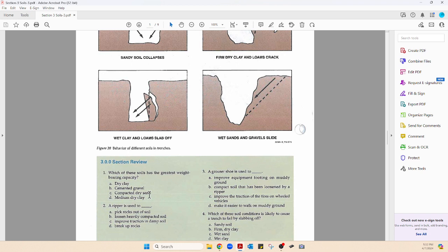You can't just put a pile of sand down and build a pad. It won't stand up on its own. But if you fill an excavation all the way up with dry sand and compact it on the way up in 12-inch lifts, you're going to have some solid weight bearing with sand.